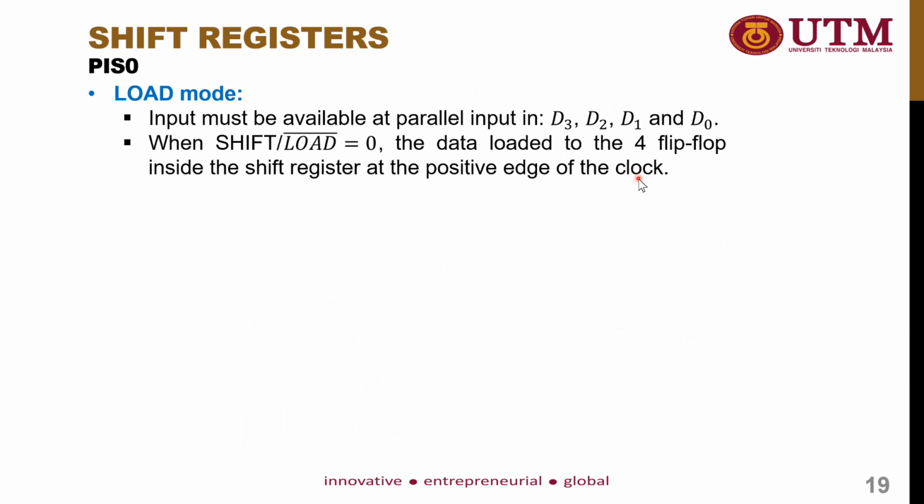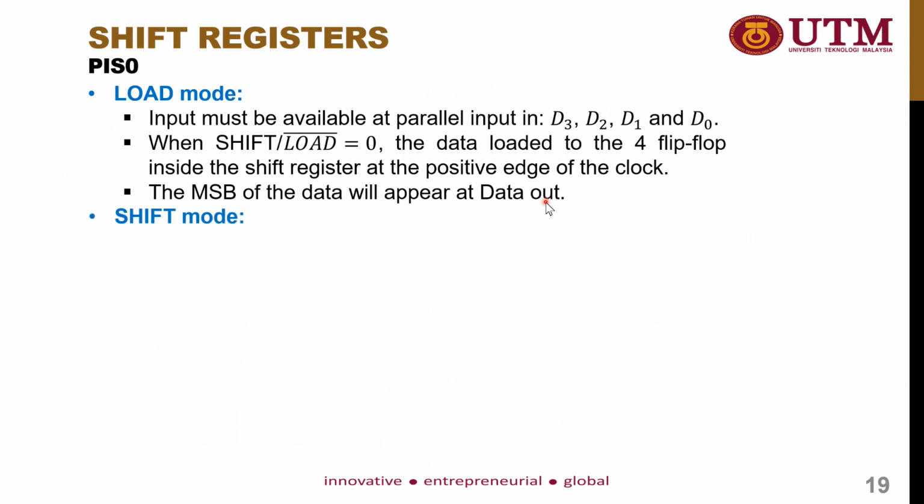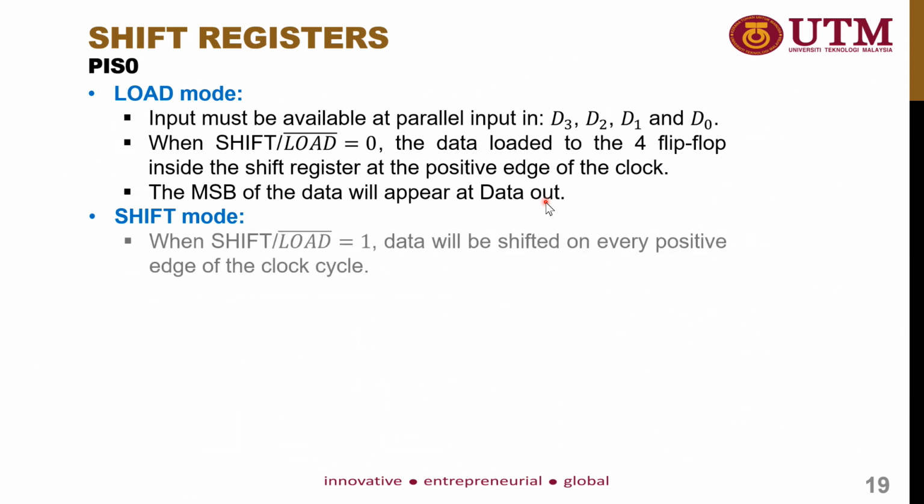So the data will be loaded after the positive edge has been detected, because it is a positive edge triggered shift register. So the MSB of the data will appear at data out. So the first data that you can observe when you are in load mode is the MSB. Okay, so next is the shift mode.